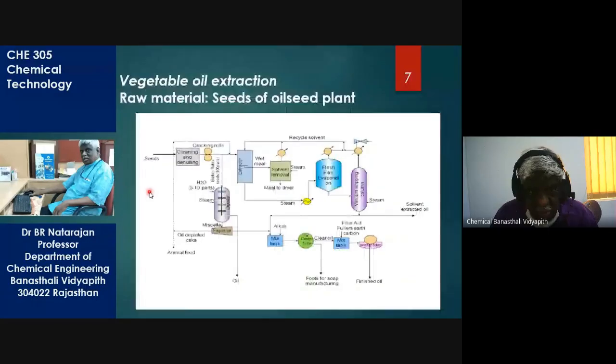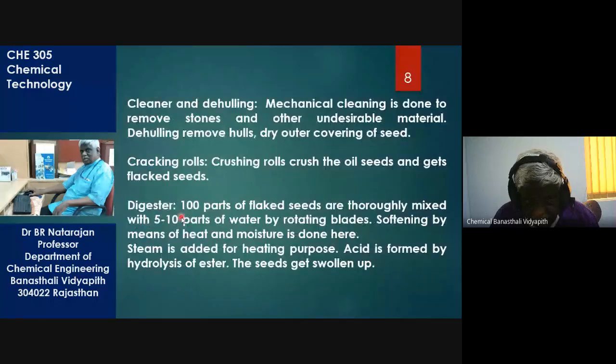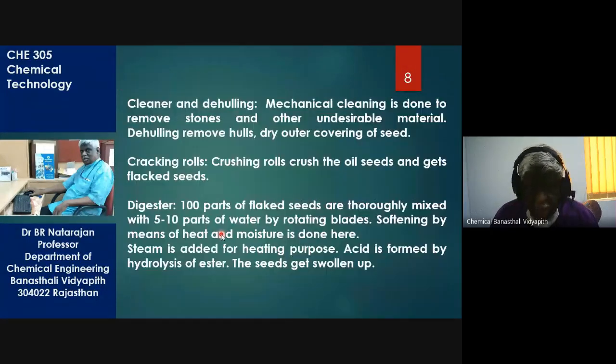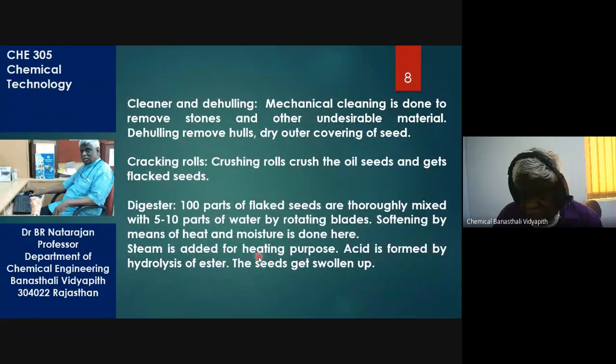Then comes your expeller. Yes, this is the expeller. This is your digester. Then comes the expeller. The swollen seed. Why is it swollen? Because it has been treated with steam, so the seeds absorb the steam and feel swollen up.